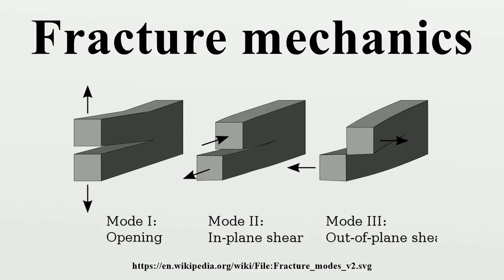The JQM theory includes another parameter, the mismatch parameter, which is used for welds to make up for the change in toughness of the weld metal, base metal and heat-affected zone. This value is interpreted in the formula in a similar way as the Q parameter, and the two are usually assumed to be independent of each other.